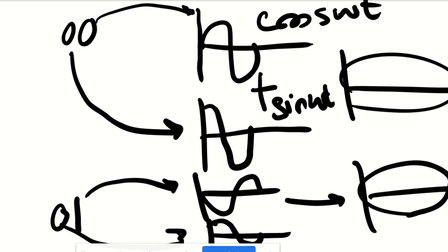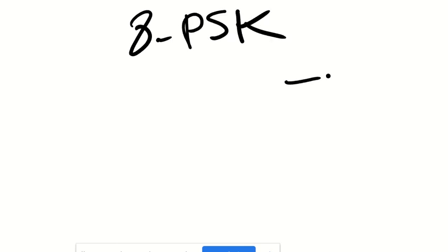Okay, so for example, as I said, you can have 8 PSK. If I tell you 8 PSK, then you automatically would know that I'm talking about 3 serial bits. And that will produce 8 different phase changes, because I'm talking about PSK. So when you hear something like 8 PSK, you would know, okay, I have 3 bits, and I'm assigning a different phase change for each.